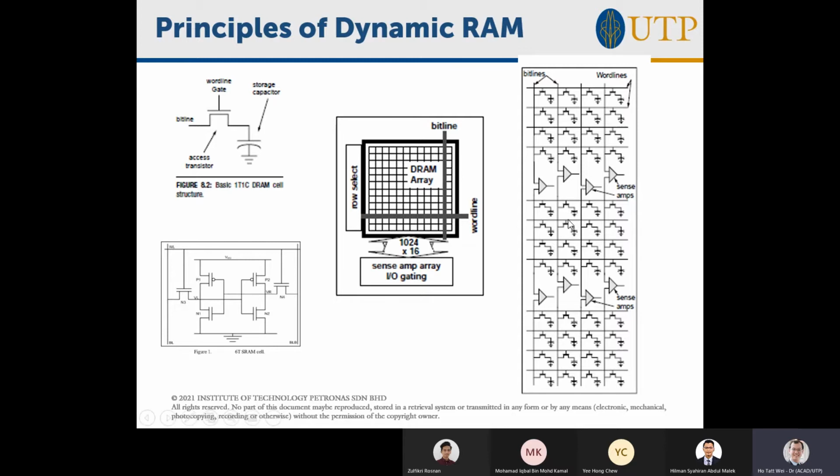So what this sense amplifier does is it detects the slight increase in voltage here, by a few tens of millivolts to 100 millivolts, and it outputs logic 1 at whatever that CMOS voltage is. So the sense amplifier actually plays two roles. One, it amplifies the signal to full digital logic levels. Number two, it acts like a buffer, like a flip-flop. It stores the value of whatever is read out until the next time you update it. You got it? This is the role of the sense amplifier.